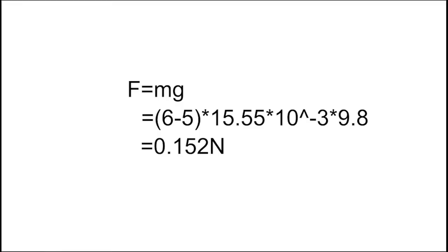It takes 4 to 5 50-cent coins to push air and 5 to 6 50-cent coins to push hand sanitizer. Each coin is 15.55 grams, so it takes about 0.152 Newton to squeeze hand sanitizer out. The force is too small, we can use that easily.